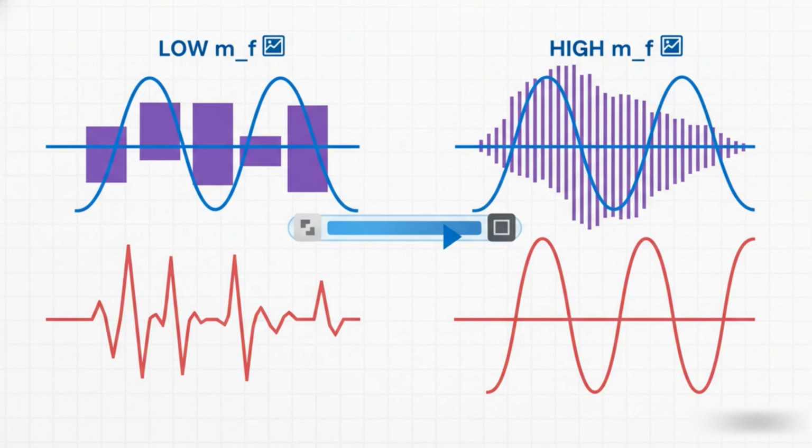More pixels give you a smoother, cleaner image. Here, more pulses give you a smoother, cleaner output current. The trade-off, of course, is that switching faster means more energy losses in our transistors, which creates more heat. It can also create an audible high-pitched whine. So engineers always have to find that sweet spot between a perfect output waveform and overall system efficiency.